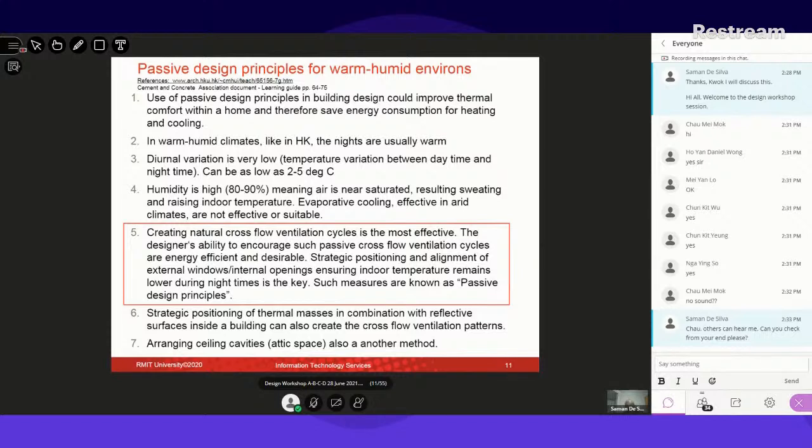So therefore, if you have about 4 or 5 people inside a house, that even the temperature can go up by about 2 degrees extra. Within the room, if you have 2 people, it can go about 5 degrees extra. So you can see that it is one of the major important things is to have the cross ventilation going.